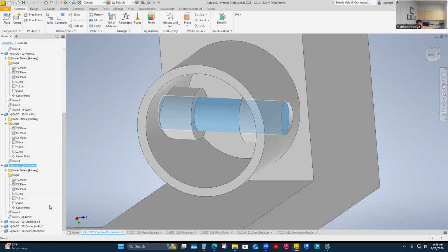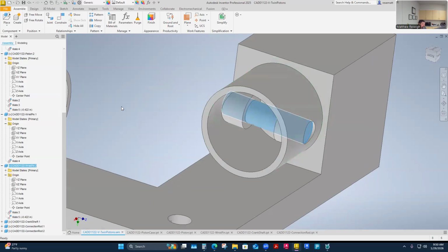Yeah, you do this all the time in assemblies too, is figure out what is the dimension between halfway. Sometimes the plane to plane isn't going to work and you're going to have to come up with a dimension. So you got to be prepared for both. You got to do whatever you got to do. The problem is that's a dimensional constraint. And so if this thing increases in size or I use it somewhere else, this is going to be an issue on a constraint. It's always going to be that much off of that base. So that's definitely not the type I would want unless I absolutely have to have it.